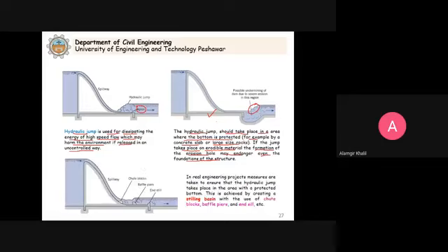Clear? So what we do is provide these stilling basins. You can see here there can be different types of stilling basins. They can include the chute blocks, the baffle piers here, and the end sill. The idea here is to contain the hydraulic jump, so energy is dissipated and protection is also provided against erosion.